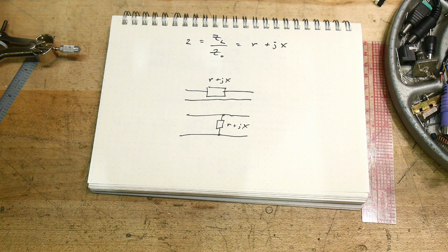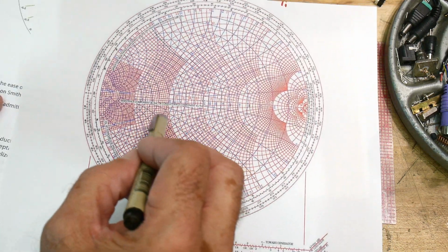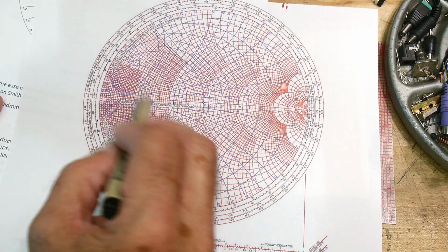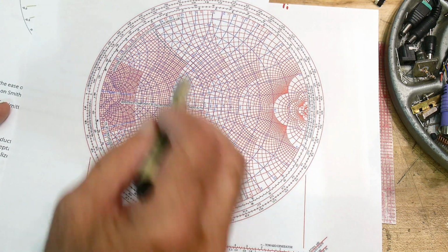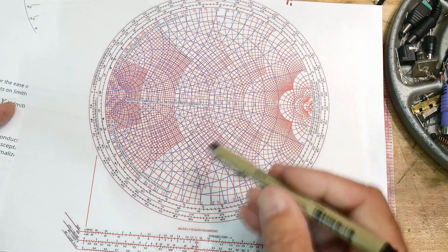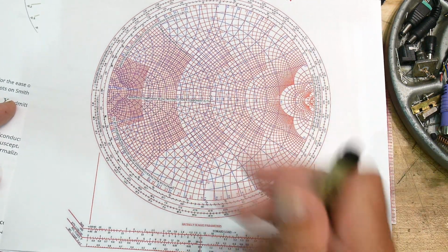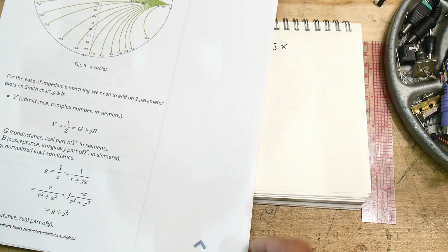All right, so when you're using the Smith chart, you figure out whether you need a capacitor in series or a capacitor to ground, or an inductor in series, or an inductor to ground, and that's why there's two sets of curves. Now, your little VNA is not going to have both sets of curves on it, unfortunately. It really should. But a real Smith chart has both because you use both.